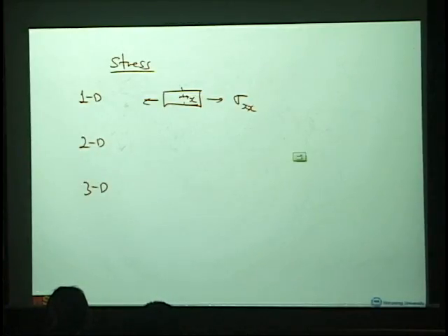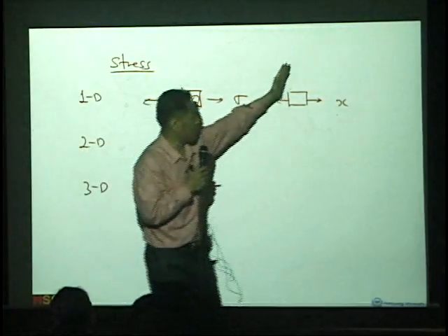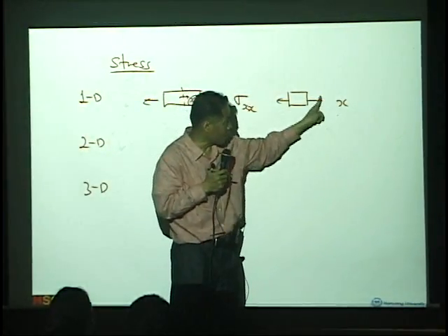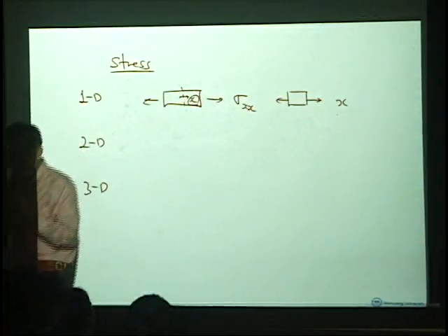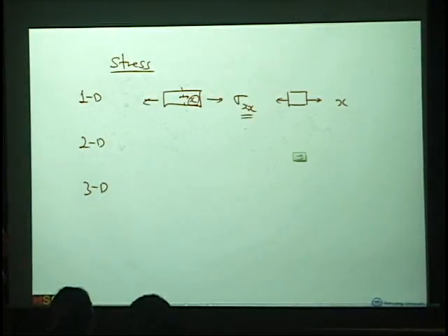If we cut it here, we only have this one component. What are these directions? Since this is x, it will be the x cross section, right? And what's the direction of the force? Also the x direction. That's why we use sigma xx. In other words, we're not going to have this component. If we did, since it is x and y, it would be called sigma yx.